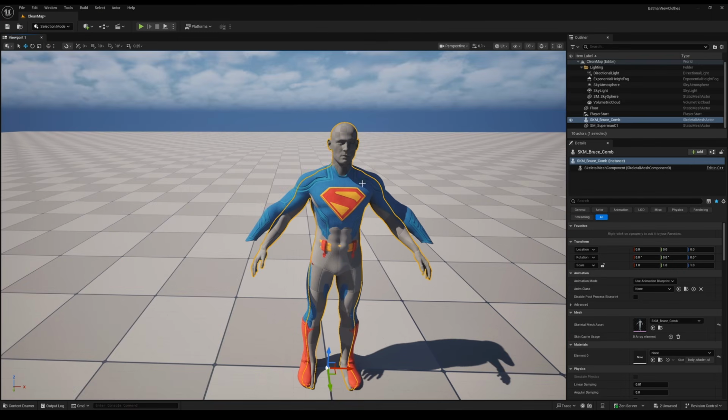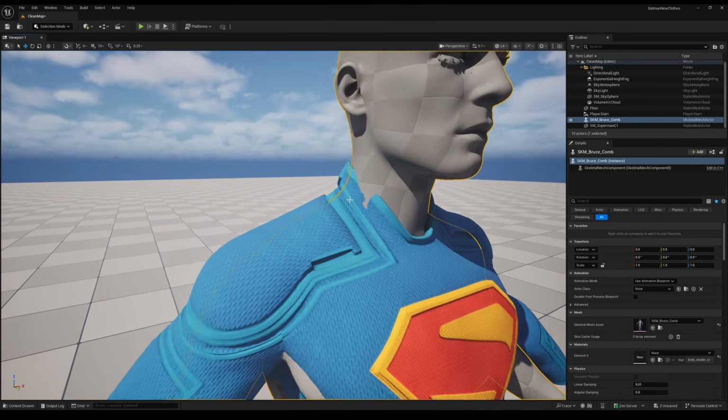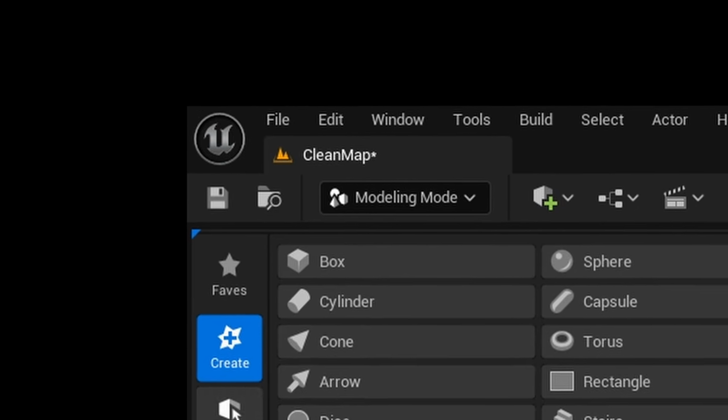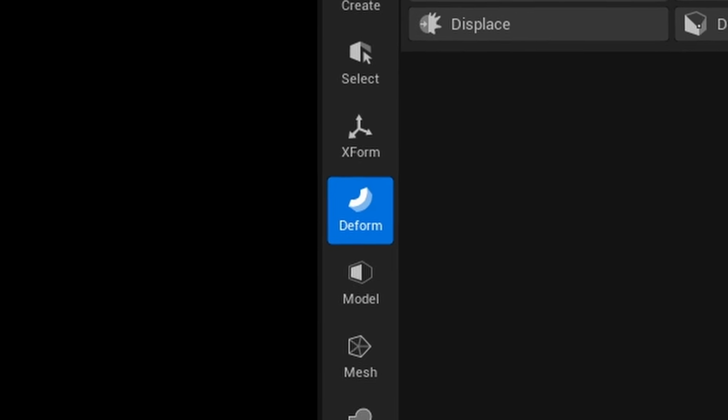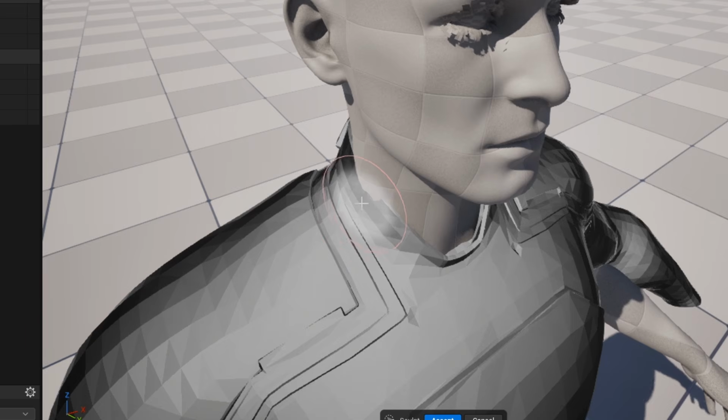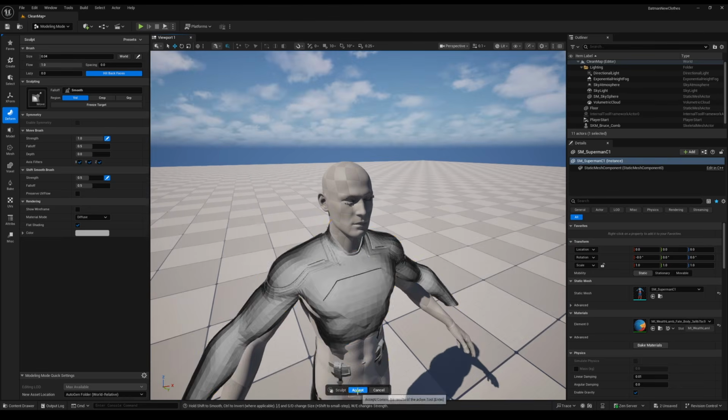Let's line it up again with the combined mesh. You see how the neckline cuts through here? So back in Modeling, Deform, Vertex Sculpt, just click and pull until the neckline is nice, like that. And accept. So simple, so easy. We are finished preparing the model.